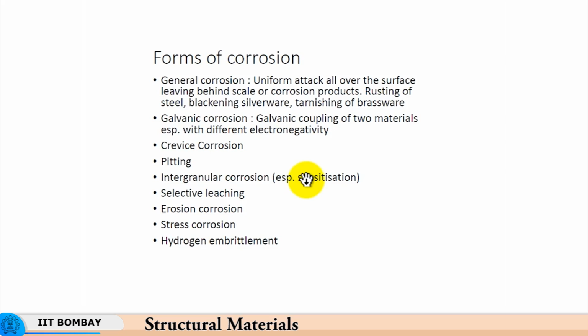Similarly, there are many other reasons for intergranular attack. For instance, you have stress corrosion, where corrosion occurs in the presence of stress. So, here the regions of high energy undergo higher corrosion rates. So, there are different reasons why corrosion gets aggravated. So, if you have just one single phase, there is no room for galvanic coupling as such.